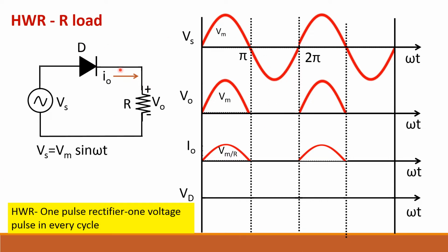So when a diode is conducting, the voltage across it will be always 0 or 1 volt. Let me take it as an ideal diode, so the voltage is considered to be 0 during this period. During the negative half cycle, when the diode is not conducting, that is when it is open, what happens? This voltage will appear across the diode. So how to find it?